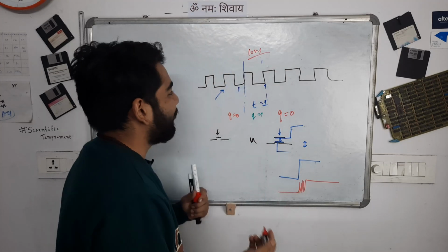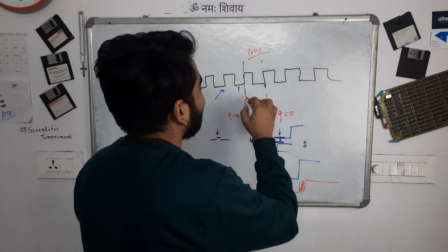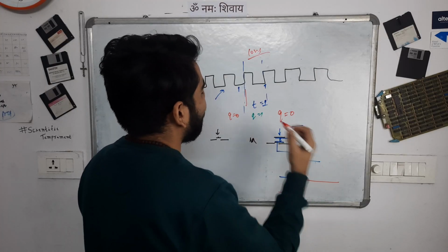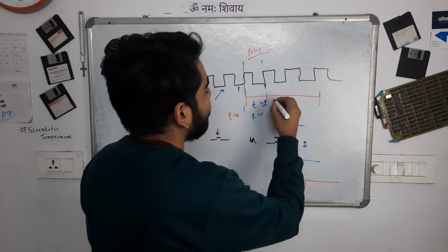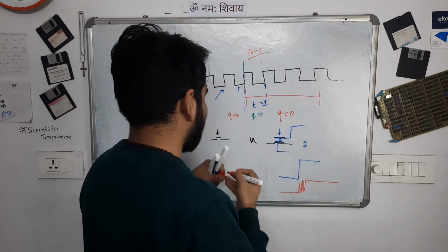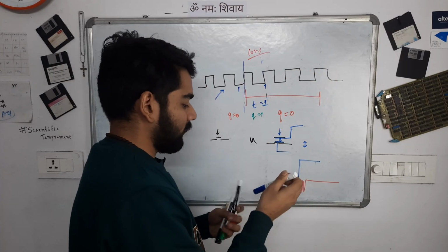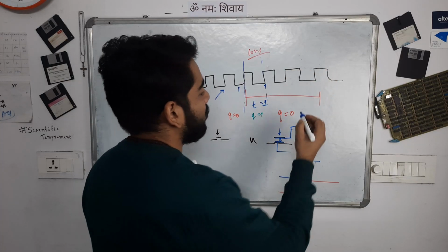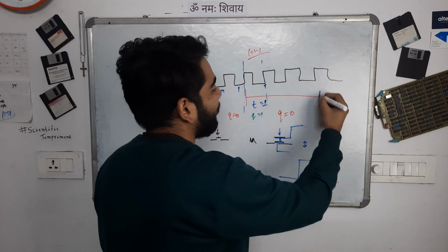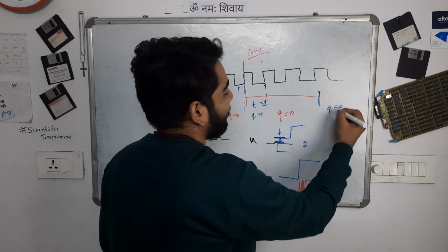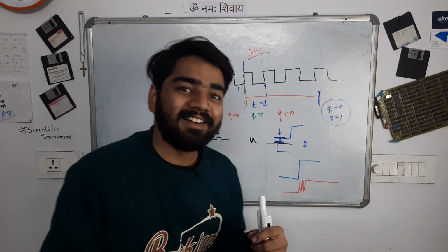In the practical scenario, I'm going to take quite a lot of time, so let's say this many clock cycles. So t is high for that many cycles until my finger was on the push button. Depending on whether the count is odd or even, the output can settle at q is equal to 0 or q is equal to 1, depending on when I lifted my finger.